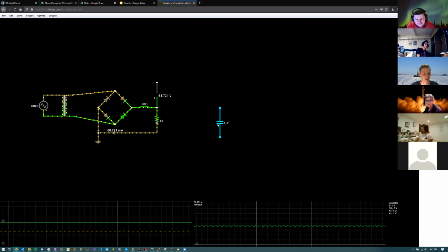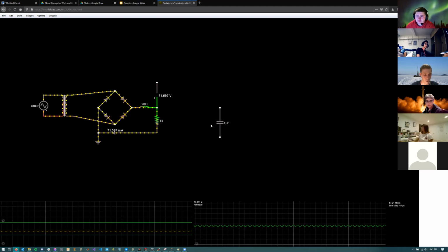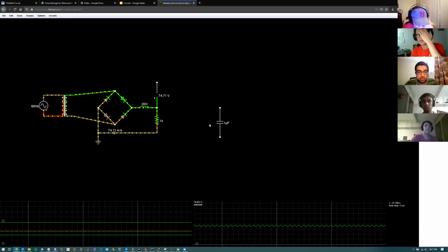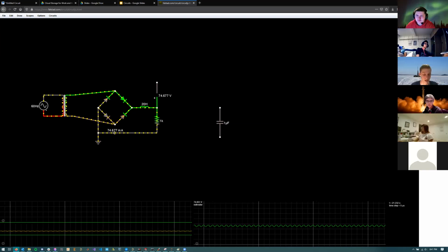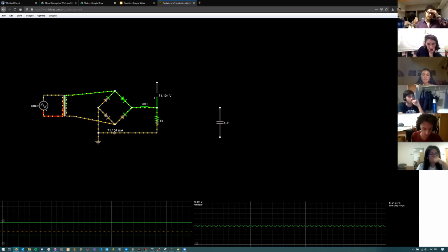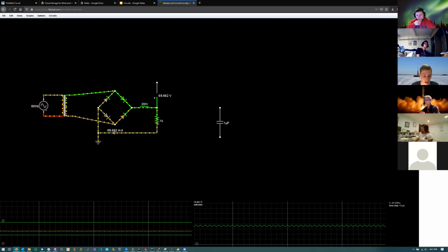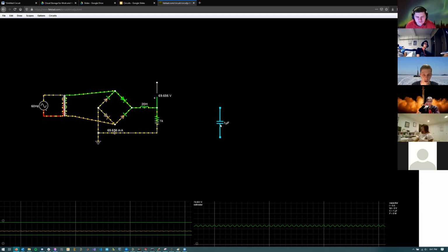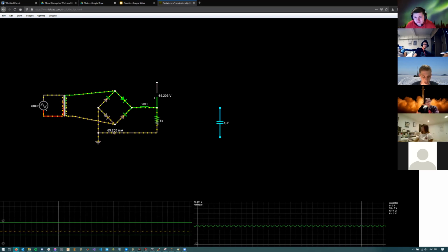Along with the capacitance, if you're using a higher voltage, the size of the capacitor must be larger as well. This is because the closer you get to the voltage limit of a capacitor, the less capacitance your capacitor will actually have.